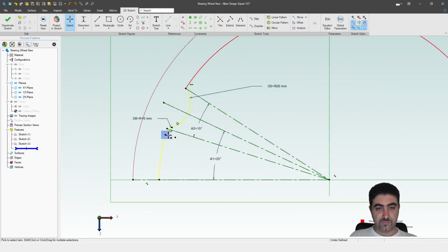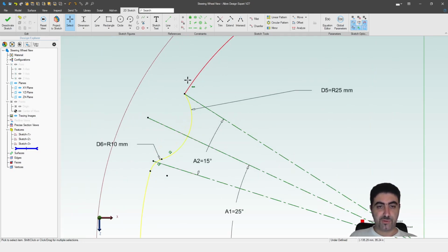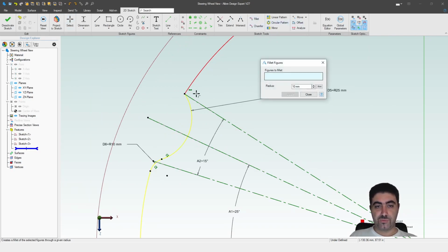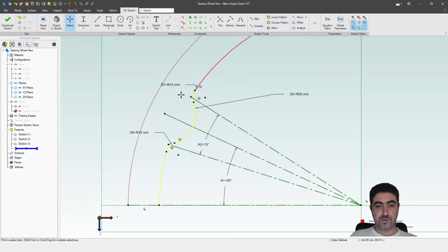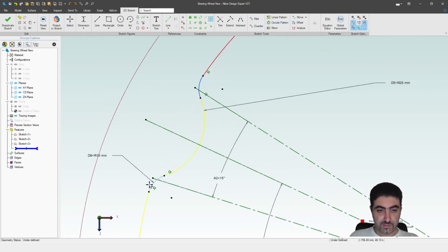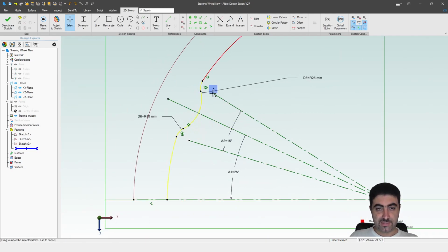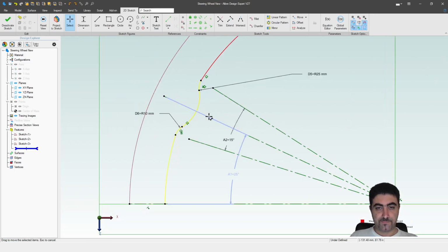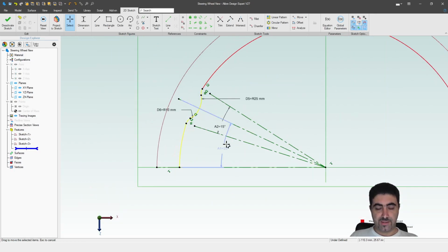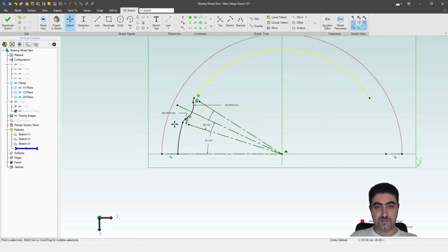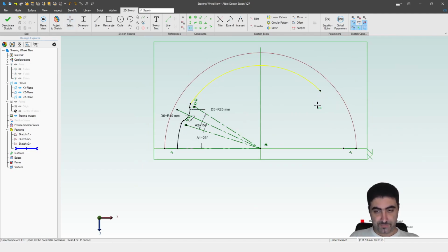And the reason that didn't go very well is because this coincident constraint broke, as well as the midpoint constraint. That also broke because the constraints are no longer there. So I'm going to delete this dimension, and I'm just going to say that these two are equal. Okay. Then I'm going to take these guidelines and stick them into these centers. Okay, again. And now remake that midpoint constraint, and we're good to go. Yeah, the horizontal also broke.